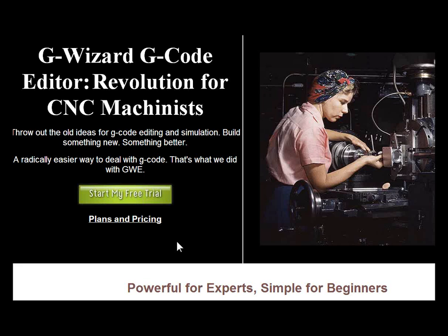One guy referred to it as he liked to hand program fixtures. They're quick and easy. Most things are laid out on a rectangular grid. Maybe he needs to drill a bunch of threaded holes for mounting Mighty Bite clamps or something, but it's just really straightforward. It was faster for him to crank that code out by hand than it was to have to do a CAD drawing and run that all the way through his CAM software, and so on and so forth.